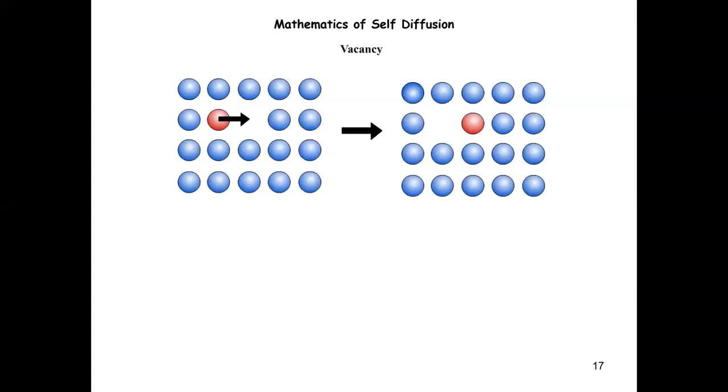Up to this point, I think we have a good picture of diffusion. We started from a very simple mechanism of solid state diffusion, which is interstitial diffusion. From a very simple physical consideration of random hopping of atoms, we derived Fick's first law and the associated important physics of diffusivity in the solid state. Then we worked with the continuity equation to derive Fick's second law, and combined these two to get the diffusion equation.